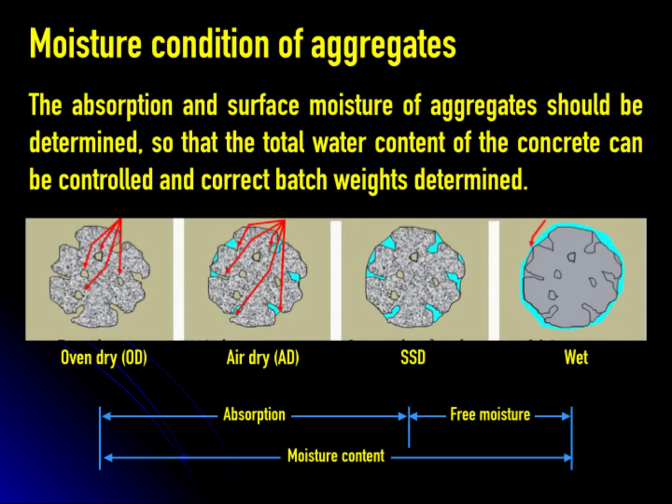So if you know the moisture content and the water absorption of aggregate in SSD condition, which is the baseline, you can adjust the content of the mixing water in concrete mixture in order to obtain the same workability.